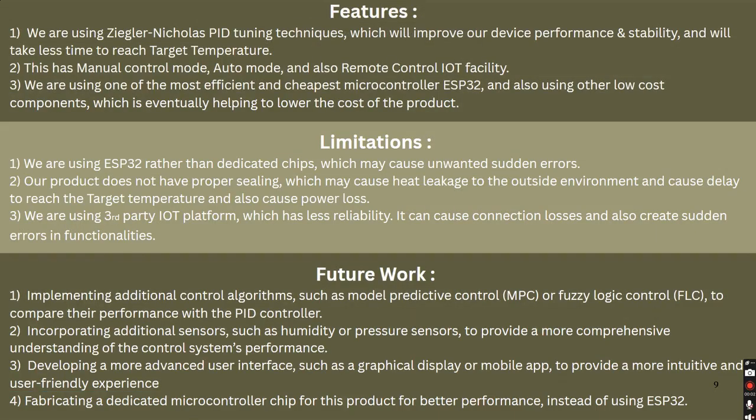So here are the features, limitations and future work for our project. Features. We are using Ziegler-Nichols PID tuning techniques, which will improve our device performance and stability and will take less time to reach the target temperature. This has manual control mode, auto mode and also a remote control IoT facility. We are using one of the most efficient and cheapest microcontrollers, the ESP32, and also using other low-cost components, which is eventually helping to lower the cost of the product.